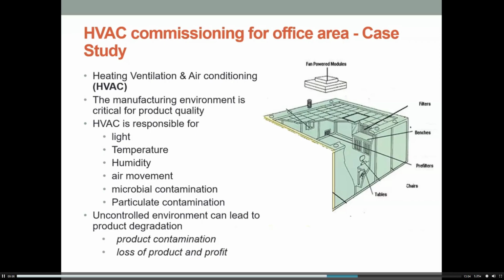Uncontrolled environment can lead to product degradation. So you could have product contamination resulting from microbial contamination or particulate contamination, or you could have loss of product and profit, because if you've got too much product being sucked out through your filters, you're going to be losing a lot of product as well. So having it working really well and appropriate for the area that it's set up in is vital for a